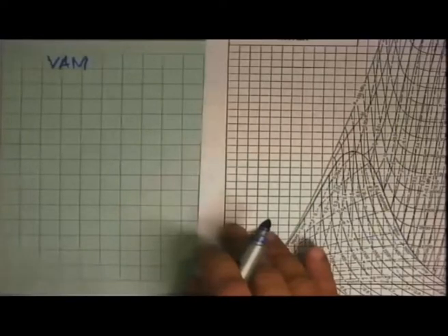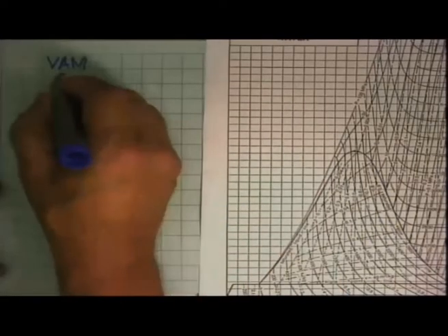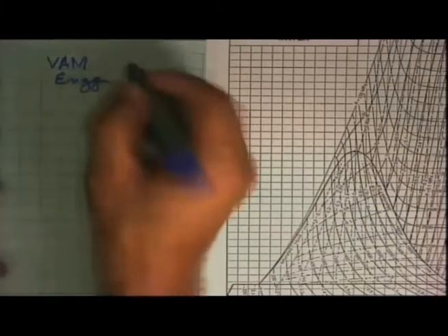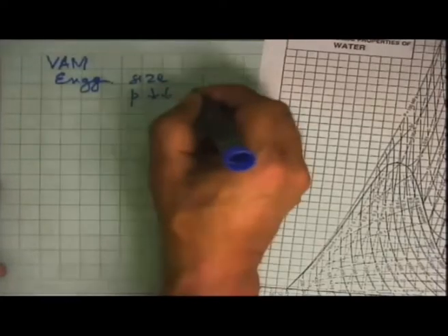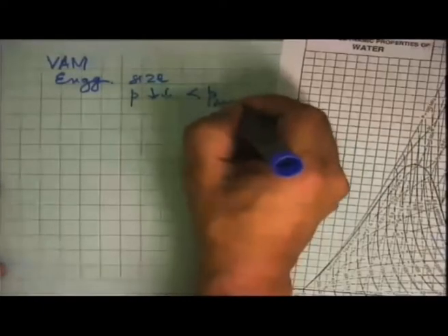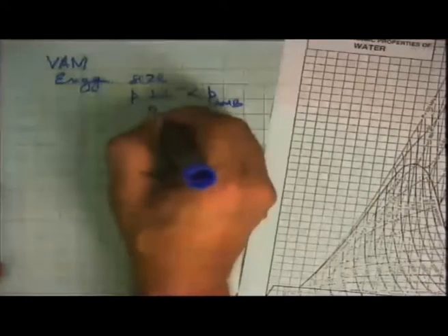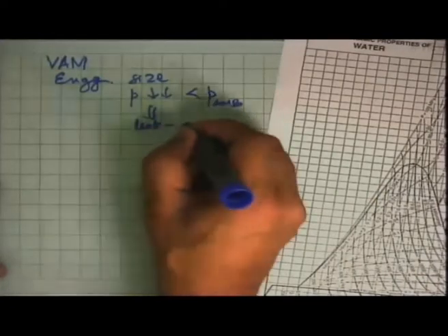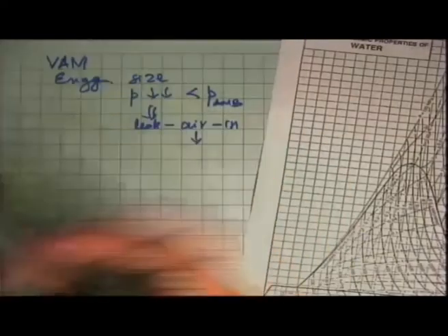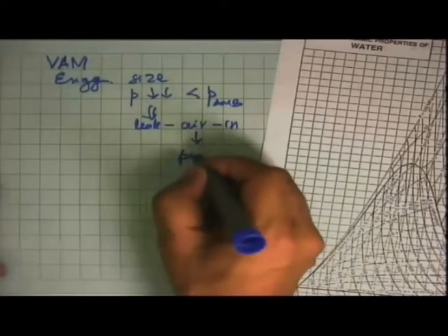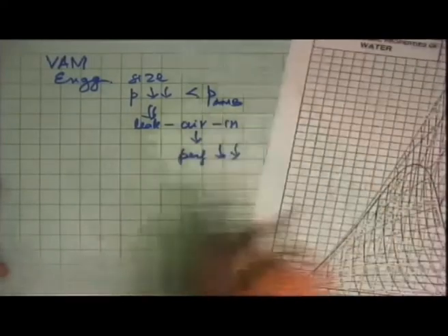You operate at very, very low pressures throughout the cycle, and you have to keep worrying that air does not leak into it. And that is where the engineering becomes complex. Now, firstly was size. The second thing, all these property diagrams tell us that pressures of water will be very low, much less than the ambient pressure, which means that I can always expect leakages, and leak will be air into the system. And once air leaks into the system, the partial pressure of air goes up, the performance of the system drastically goes down and we have a big problem.